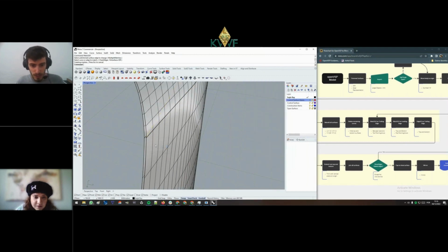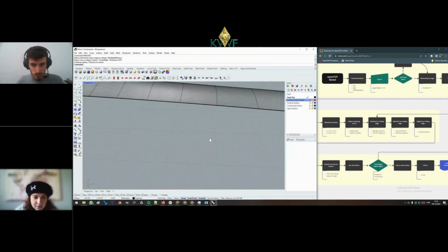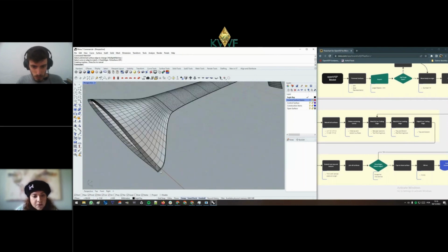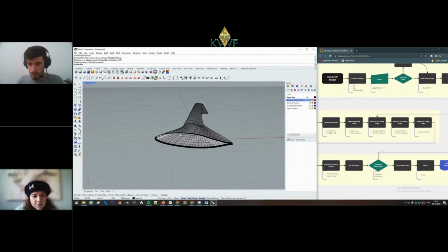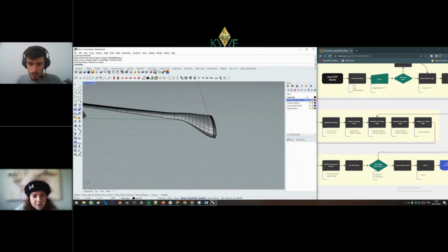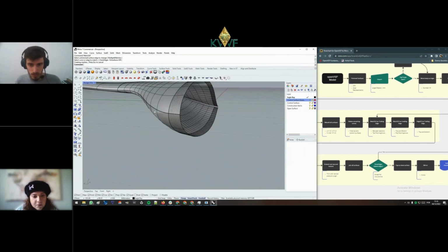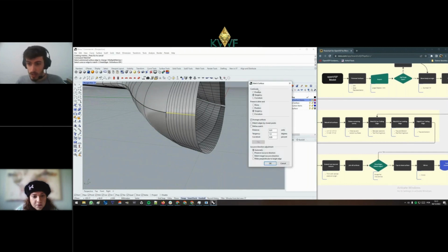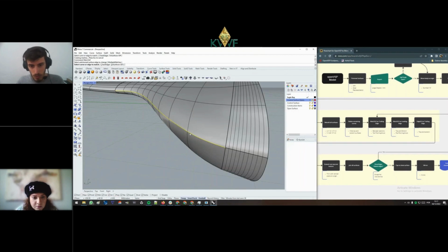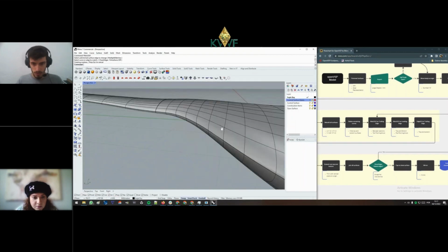So we've matched everything for the trailing edge. Now it shouldn't have any step, and the shape itself didn't change too much. We'll do the same thing for the leading edge because it's not very lined up as well. But this time we will use position for continuity on one end and the other end with tangency. The rest of the settings are the same. And we do this for every top and bottom pair of the leading edge.